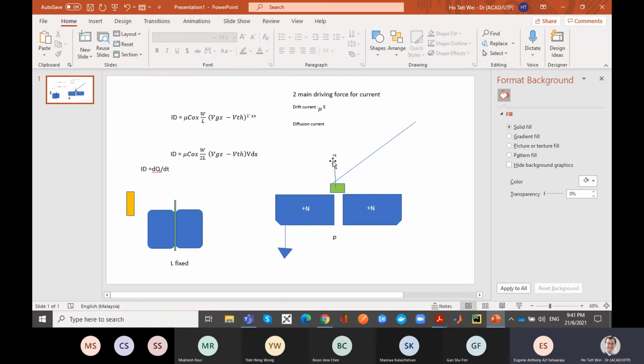Yes. Okay, so when you have 0 volts here, there is no conducting channel. Your MOSFET is turned off. It's not conducting. But there is a non-zero voltage on the base terminal of the BJT, which has a collector, emitter, and base. And guess what? When there's a non-zero voltage on the base terminal of a BJT, you've got current flowing through here, right? That's how we estimate the leakage current of a MOSFET.